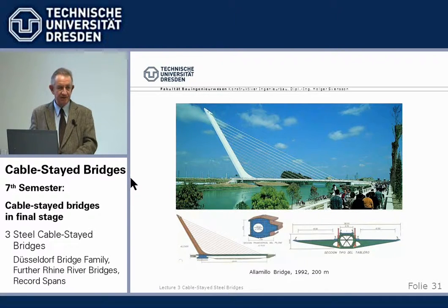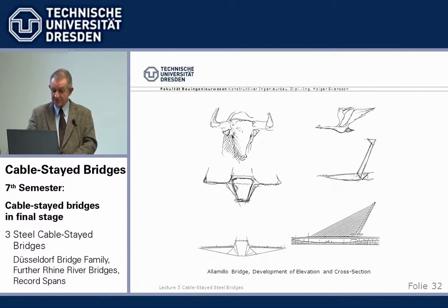Unique. Now that means for permanent load, the system is balanced. The vertical forces here balance the weight of the steel beam. But of course, for live load in the main span, it has to act in bending, which is not the flow of forces we consider appropriate for cable-stayed bridges. But it is a sculpture.